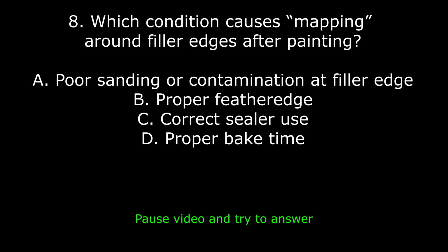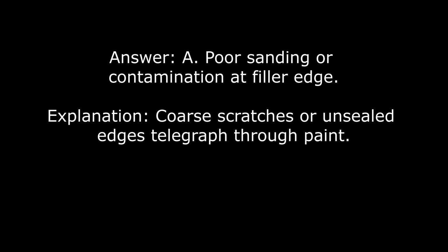8. Which condition causes mapping around filler edges after painting? A. Poor sanding or contamination at filler edge. B. Proper feather edge. C. Correct sealer use. D. Proper bake time. Answer A. Poor sanding or contamination at filler edge. Explanation: coarse scratches or unsealed edges telegraphed through paint.